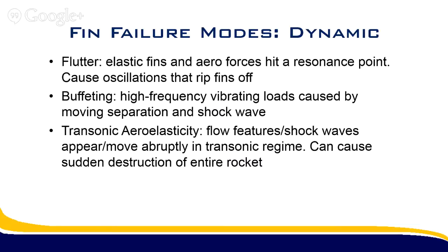Then you also have buffeting, which is kind of a high frequency vibration that causes a lot of shaking, and this happens near the sound barrier. You hear stories of a lot of the early test pilots talk about an extreme shaking when they got near the sound barrier, and this is because you have moving flow separation and shock waves.